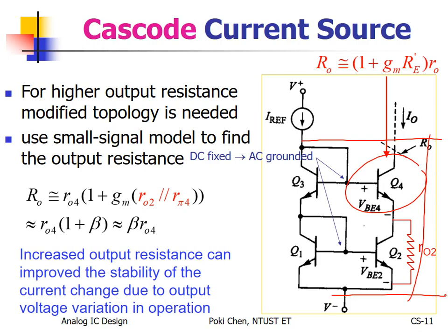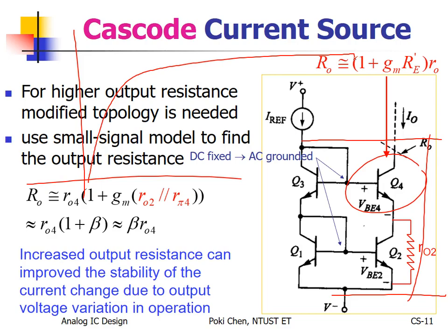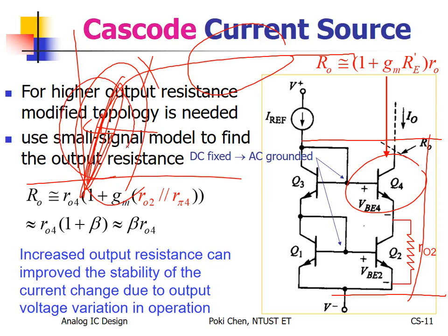Okay, that's it. Yeah, you can see the real, okay, I forgot to show you. That is the real property for current source or current mirror. This is so-called headroom. It means what? Before some point, it is in such kind of very bad region. In MOS, we call it triode. And in BJT, I forgot. BJT called this linear. Maybe this is the so-called saturation region for BJT. The definition is totally reversed.